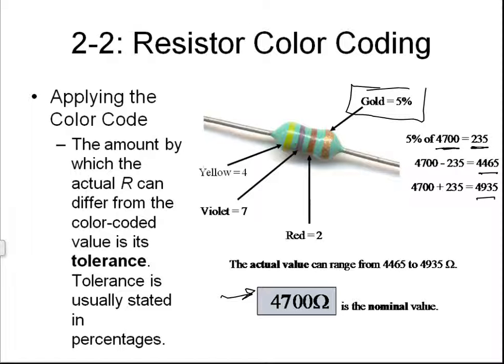So you see, a resistor can have quite a large swing, depending on its composition. In this case, it's a carbon comp. A big problem I have for some of these is that it looks like green, violet, and brown to me. So you have to also pay very, very close attention to your color codes. This is just because I'm a little bit partially colorblind from just too many cracks to the skull over the years.